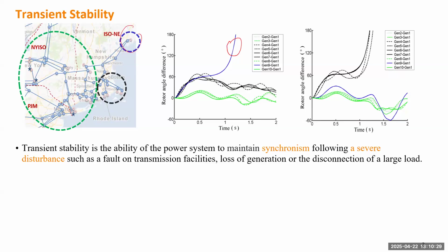This one generator, the first figure just indicates this generator. If you have some disturbance near that group, that can make that power plant fly away, right? But the remaining system, even if it forms another two coherent groups, still stays pretty close. So the rest of the system is still stable, but this generator will be tripped. So this is one scenario of a single generator losing transient stability.